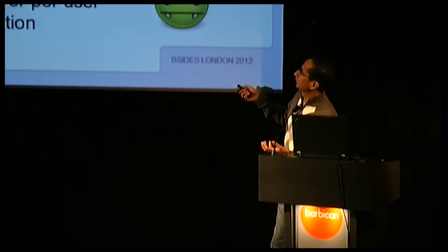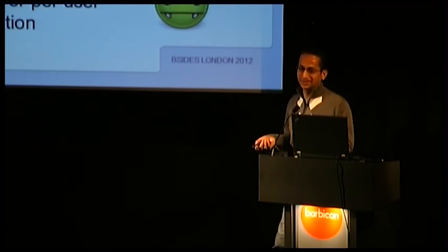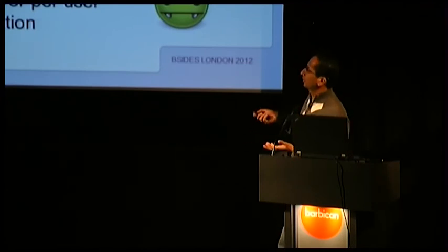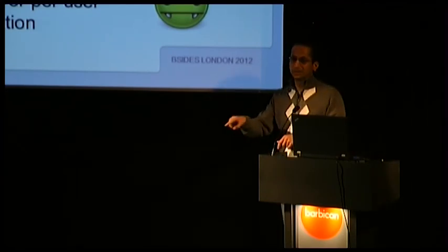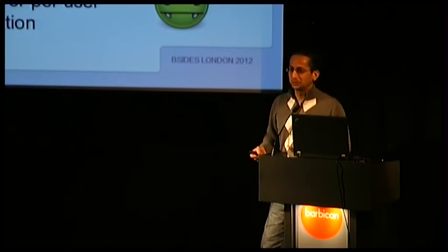to talk here. Of course, it can use protocols that we just saw, because the protocols also don't have any authentication or access control. But using the protocols may be tricky, so a lot of times the virus could just access the HMI system and click these buttons, which usually the operator would do. Of course, this would require the virus to know what SCADA system is being used and how to manipulate it. But from Stuxnet, as we saw, there are viruses written which know exactly how SCADA systems behave.